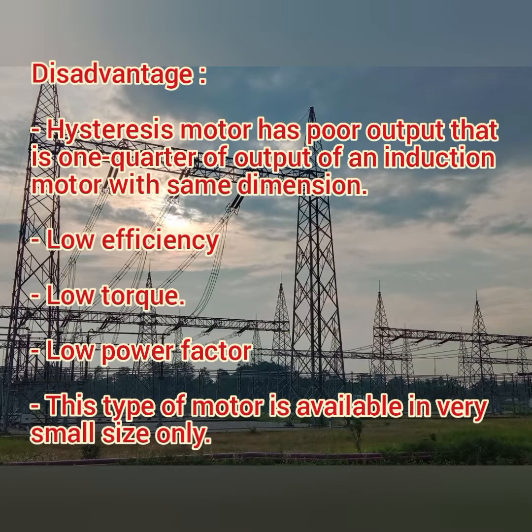Next, the disadvantages of the hysteresis motor. The main disadvantage is that the hysteresis motor has a poor output, one quarter of the output of an induction motor with the same dimensions. Then it has low efficiency and low torque. In this case, the power factor is also very low when compared with other motors.